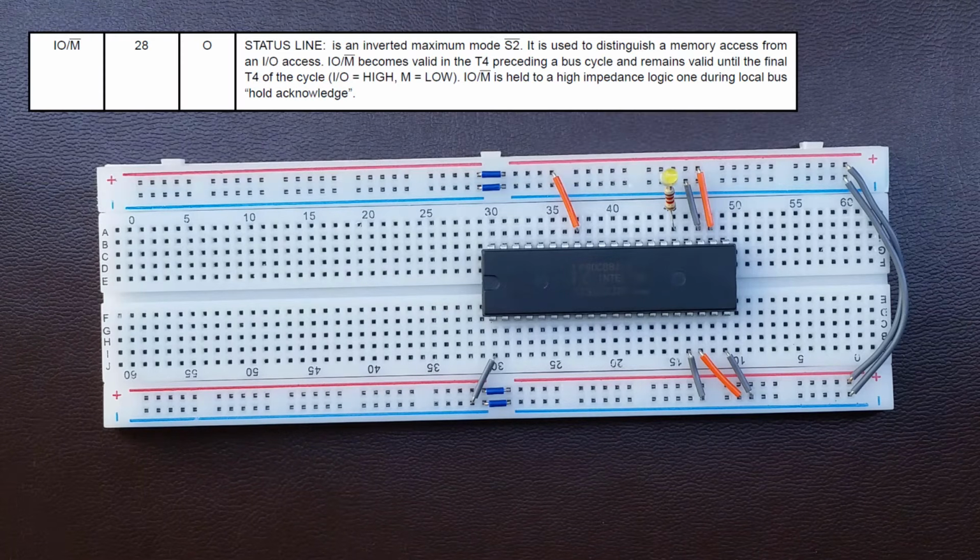Pin 28, IO/M, is an output telling us whether the CPU wants to transfer some data with the memory or the I/O peripheral. That is because, unlike the other CPUs of that time, x86 has a separate address space for the memory and the I/O. The pin selects which one is in use at the moment.